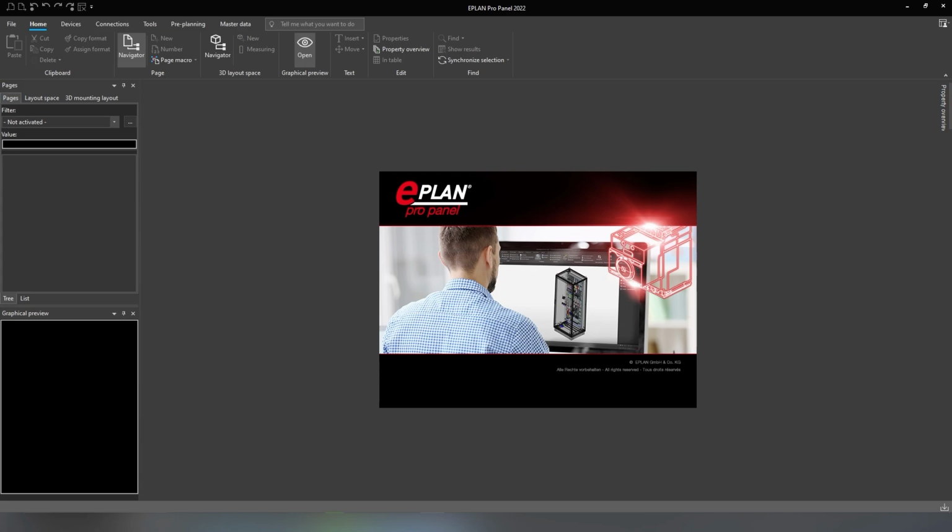And one thing you should note when you're using the macros project is that cross-reference and connecting information cannot be done. So basically your interruption points do not work well. If you have a relay and you want to display the contacts of the relay, it doesn't work in the macros project. Well, it doesn't work at all, because it's a macros project.